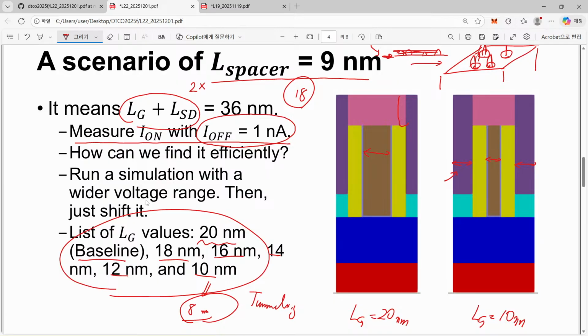If, for example, let's say gate voltage and drain current, and this one is 1 nanoampere, and our actual curve just looks like this in this semi-logarithmic scale. So this is log of ID, and now we have a straight line. We wanted to have this curve. When gate equal to 0, our current should be 1 nanoampere.